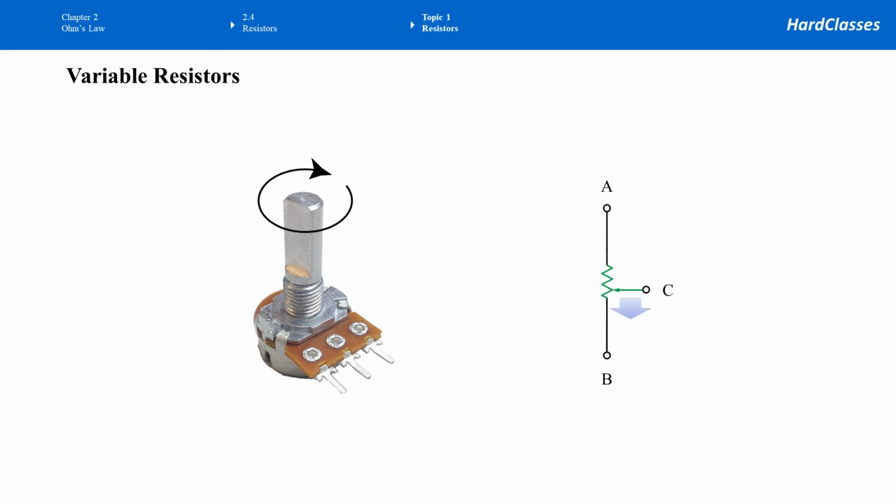As you can see, the potentiometer has 3 terminals. To use the variable resistor feature, we just need to use the center terminal and the terminal on a side, such as B. If you select terminal B, and terminal C is like in the schematic symbol, moving terminal C upward, as you can see, we are using more of the green region, so the resistance value increases.